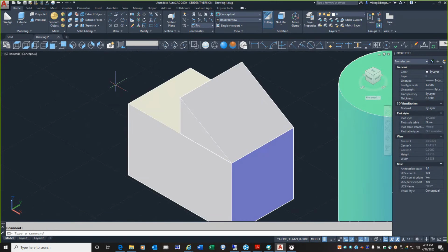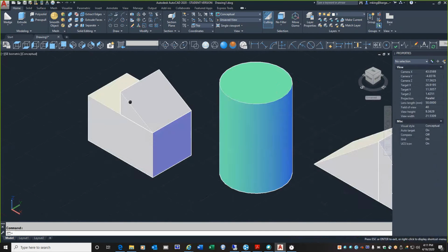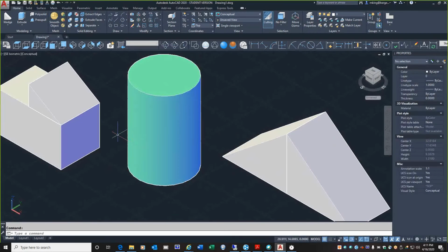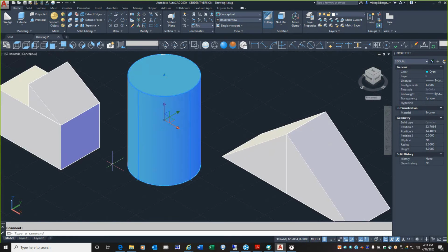All right. So, playing around with some solids, we have the ability to modify these shapes to some degree. For example, go back to the cylinder and click on it, and you get grips on the quadrant points around the base and at the top. Hard to see there, but, oh no, I'm sorry, it's just at the base. But at the top we have this up arrow.